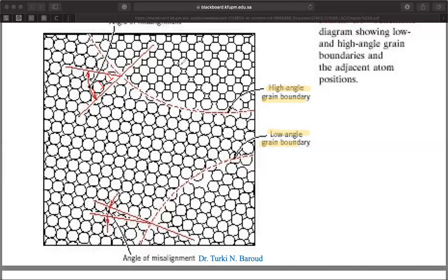So this pileup of dislocations will act as a stress concentration that will initiate new sources in the other grain. The message from this is that grain boundaries have their own effect on the strength of the material, because they place more obstacles in front of the dislocation, and those obstacles might not be as effective if you have a low angle grain boundary.